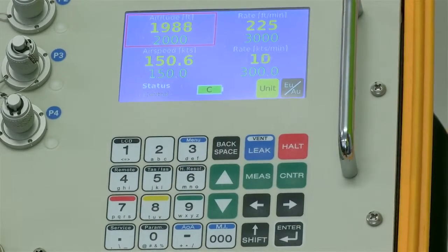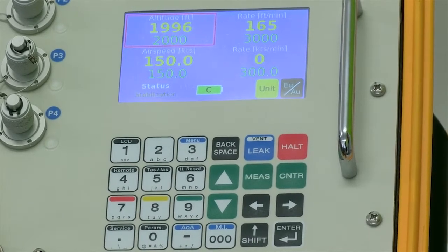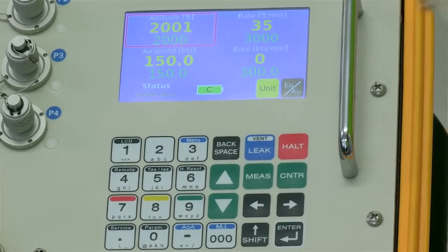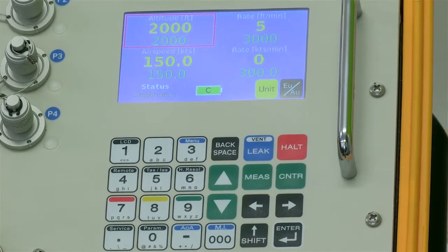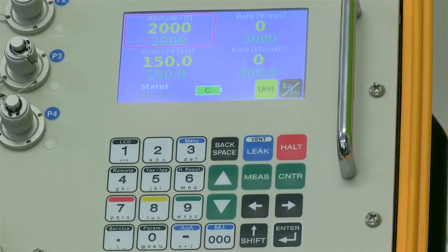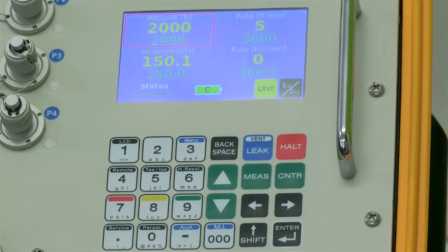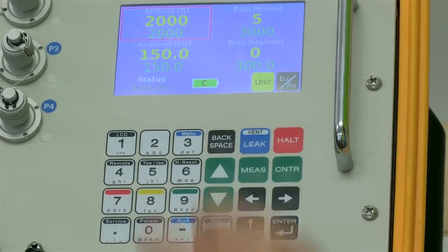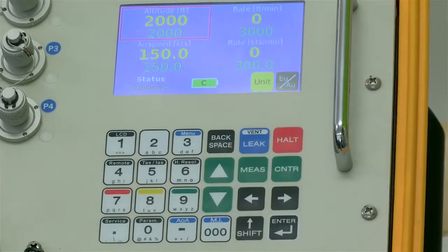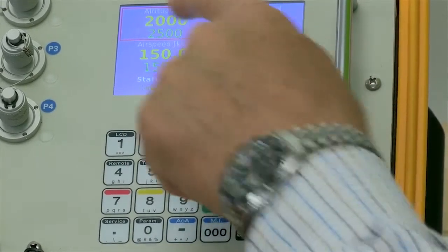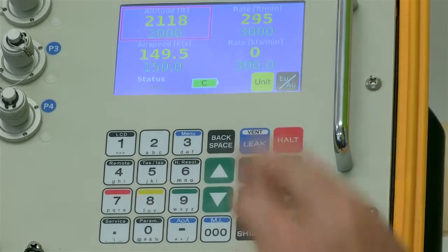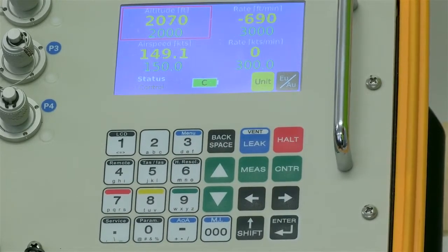For example, we call for 2,000 feet. It might be that you're testing an instrument where you would like to investigate if there was something a little strange with it. Thinking of the older traditional instruments, maybe it's a little sticky. Maybe it's not moving on as smoothly as it should do. Well, with these keys, you can program that every time you press a key, it increases the altitude by a set amount. So, for example, I can press that and it's going to go to 2,500. Or come down again and I come down to 2,000. You're able to program these keys so that the value of those keys is in line with what you would like to have yourselves.